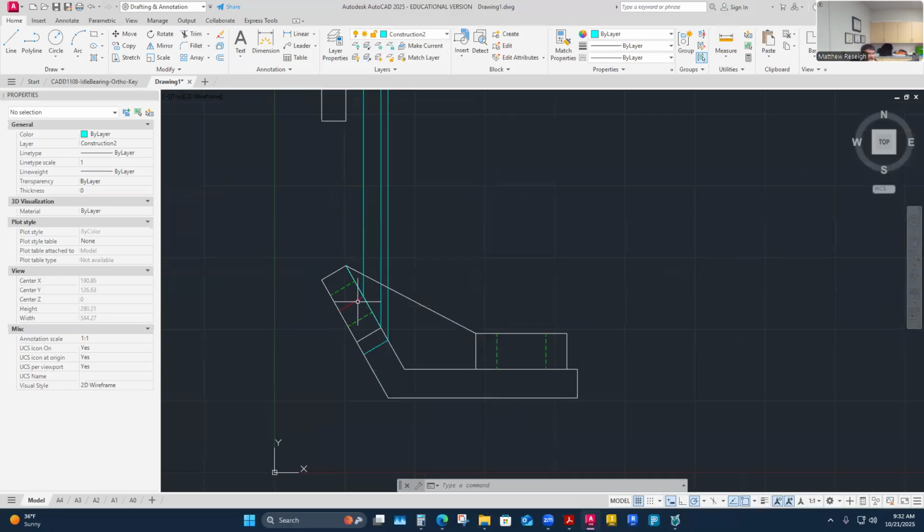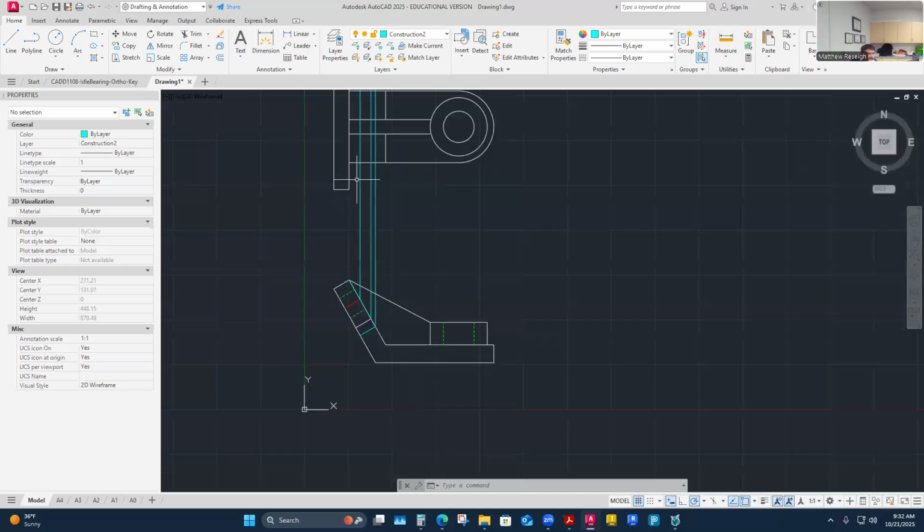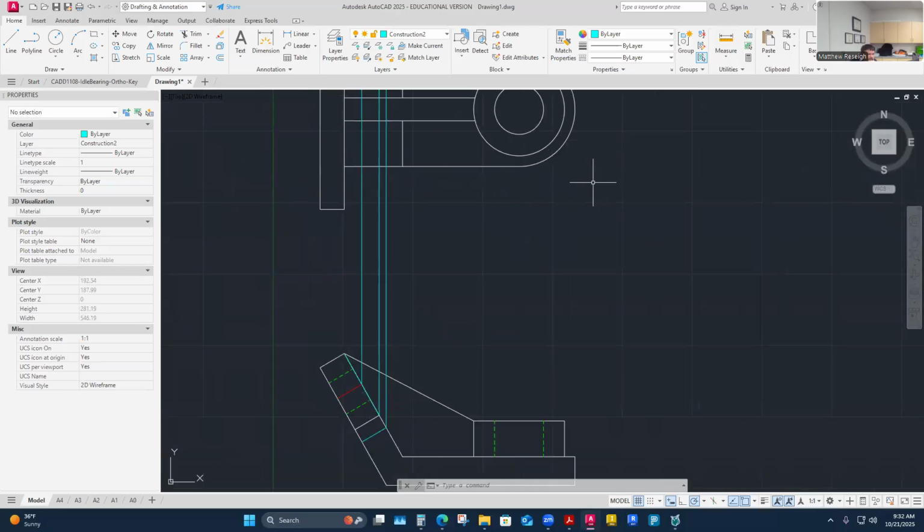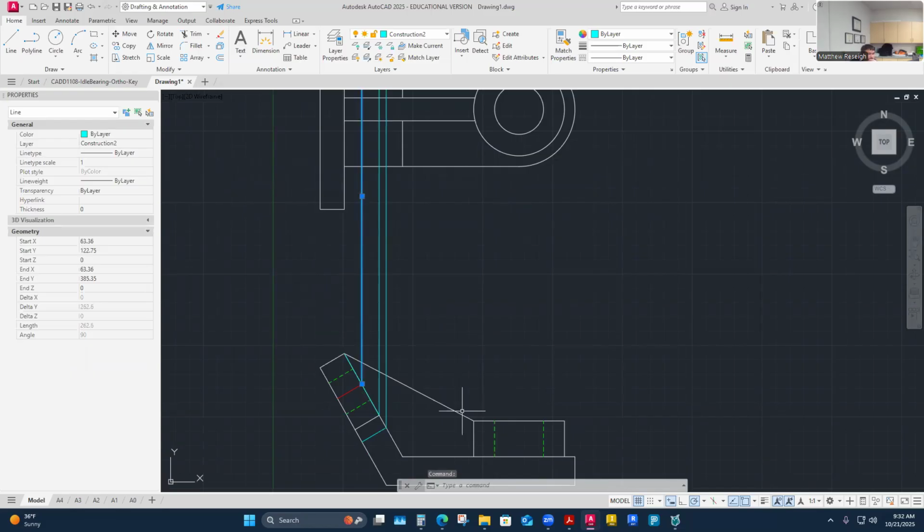Center is center. Everything's concentric here, the hole and the ear. So I've projected that center across this way. What I want to know is the crisscross center, where that center line crosses this center line. I'm probably given that information. The radius is 25. So if I just come over 25 from here and put in a cross, I'll have a center point to base an ellipse off of. So I'll show you.